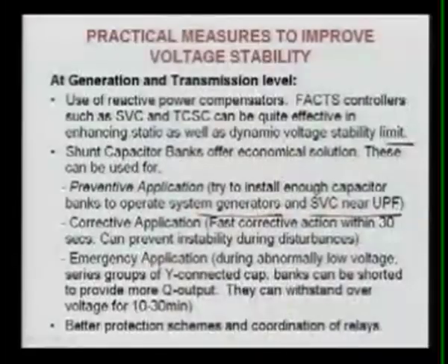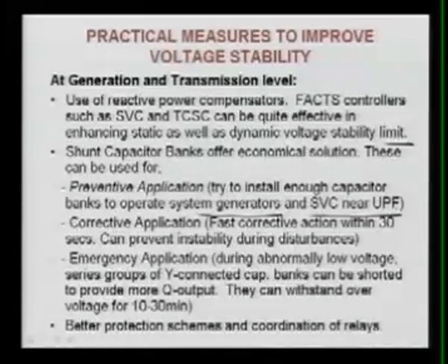So we can use the series groups of Y connected capacitor banks, which can be switched in to provide more Q output, and they can withstand over voltage for 10 to 30 minutes. So we can use some groups of Y connected, that is, star connected capacitor banks. They can provide more reactive power support, and then we can avoid the emergency situation. So we require a better protection scheme as well, and also the coordination of relays.